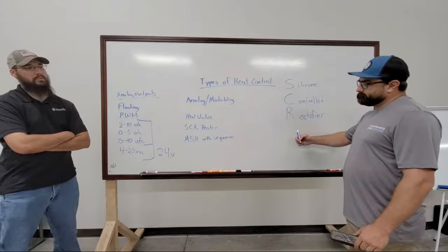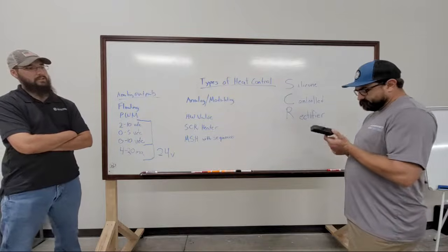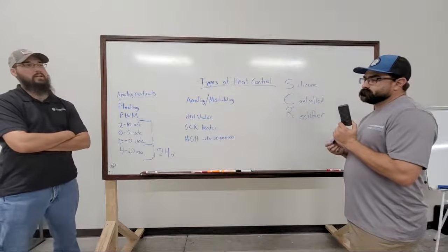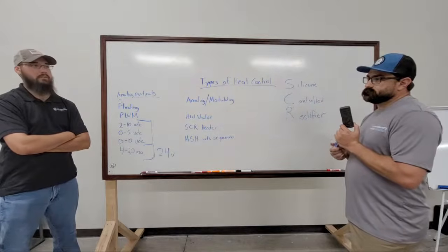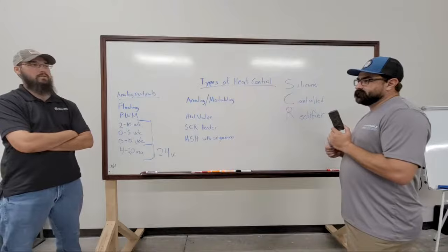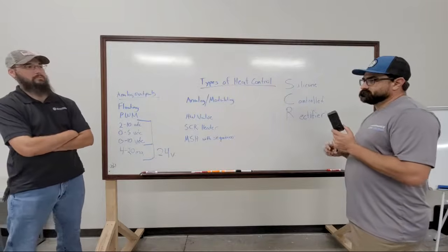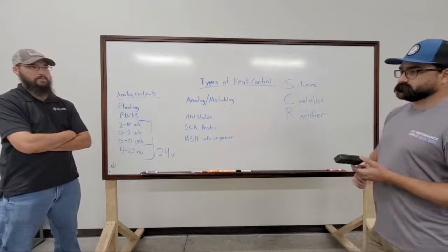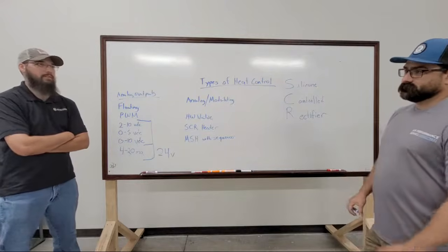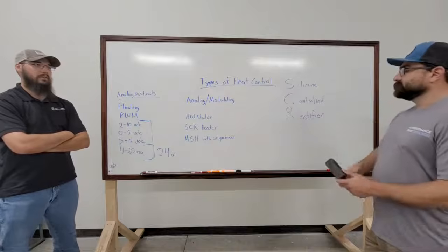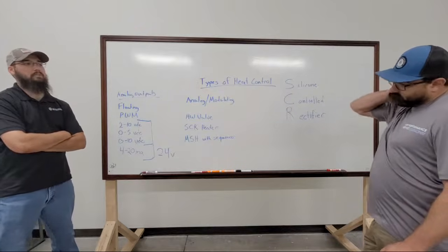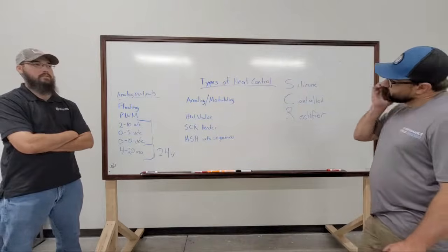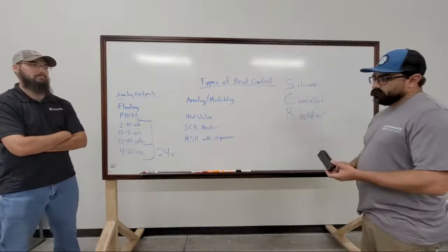It's basically just a solid state relay. At the end of the day, it functions very similarly to a triac, just a really big one versus a very small one. So it's rated for 30 amps versus a regular triac on an automation controller might be rated for half an amp, at milliamps. So that's the simplest version of an SCR that really applies to anybody in the field without being an electrical engineer.